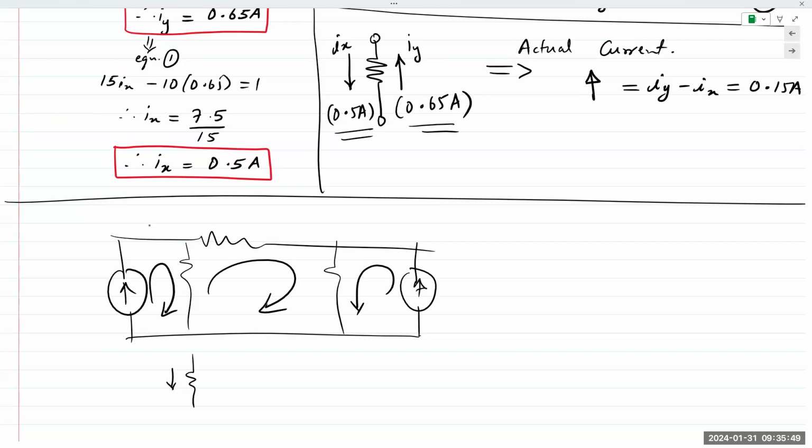So I have two currents, one going down and one going up. But I look at the current source, and I only have the mesh current. That's it, nothing else. So the mesh current for this first loop and for this third loop, or the third mesh, is the current source. And that's it. You just write one KVL expression for this middle mesh, you plug in the values and you solve. One equation answer. I think it takes less than like 5 minutes.